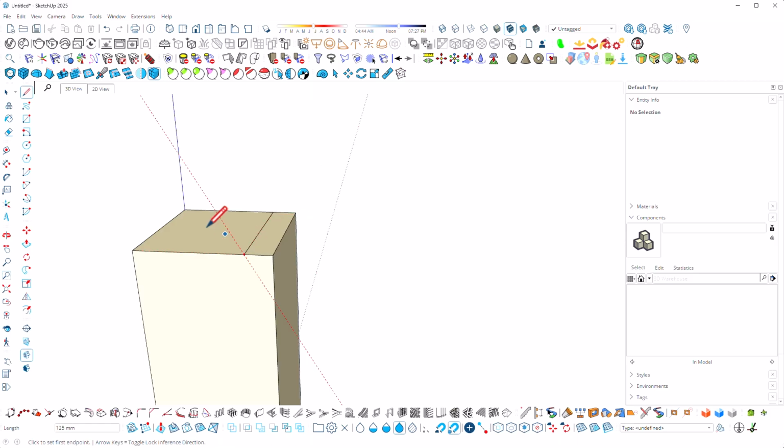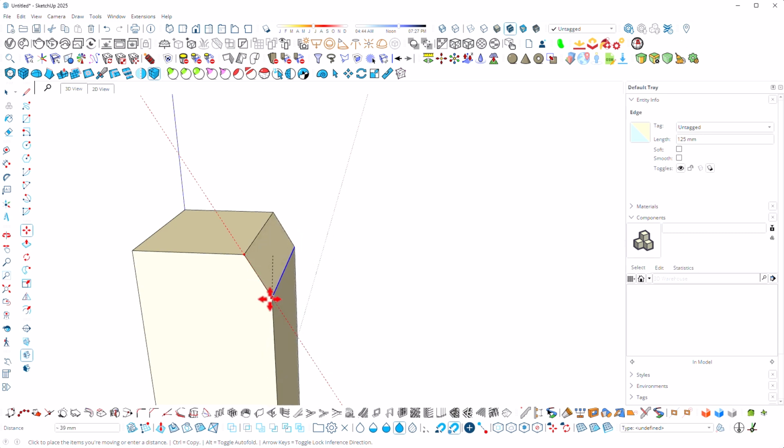Now if I just click the selection arrow here, if we want to manipulate this line, we'll select that, then go to the move tool, select the move tool, click on the corner and drag that corner down. Now you see there, as I started dragging, the dimensions got a little bit squirrely.